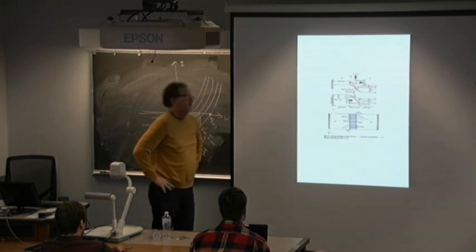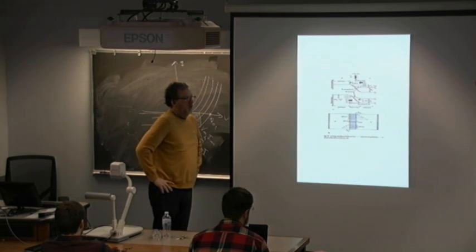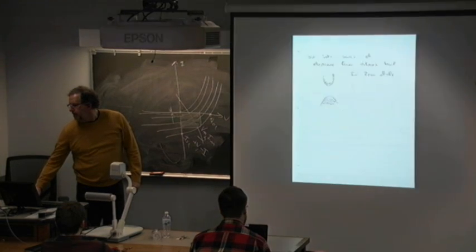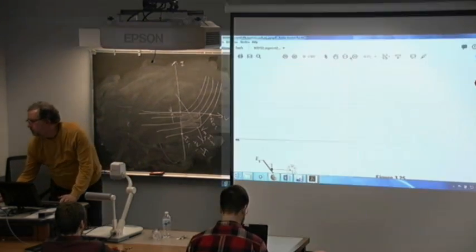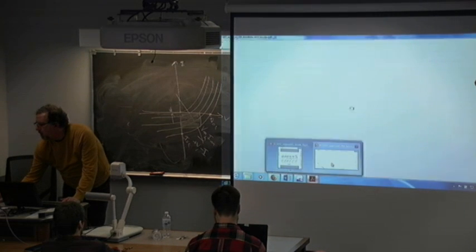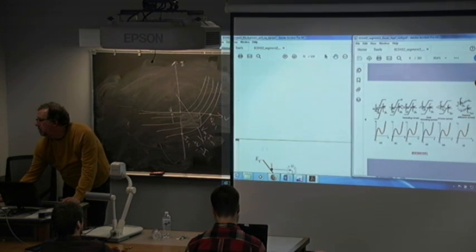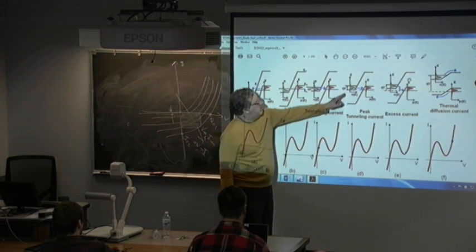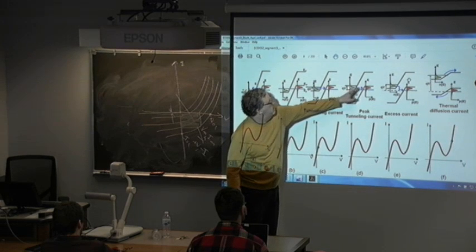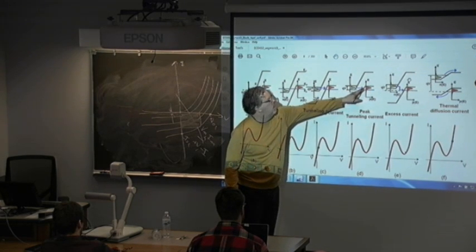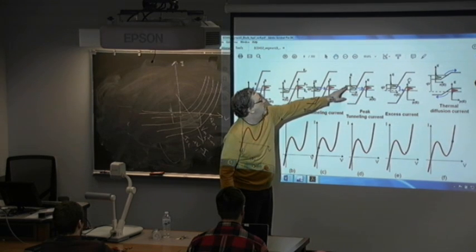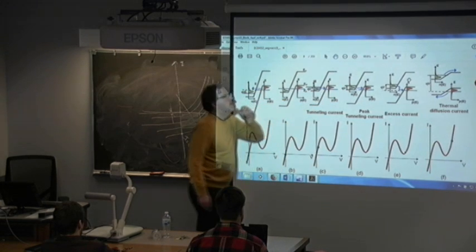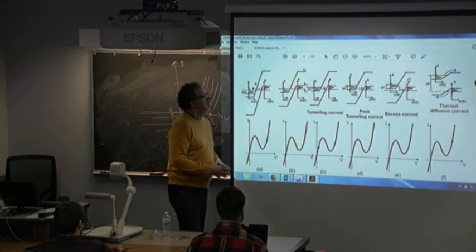So is the variation in the condition on that hump in the diode equation for the tunnel diode due to the widening or the shrinking of the depletion region then? Because when you say fitting the keyhole, it seems that the energy states matter, because the three conditions for tunneling are available carriers, available empty states, and a small distance in between. But you said earlier that the Fermi function and the density of states do not change.